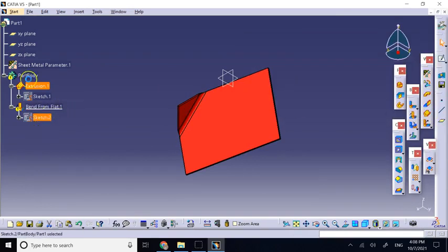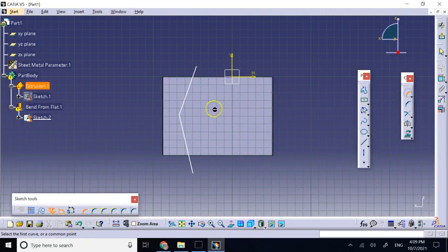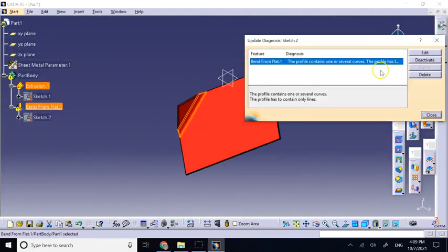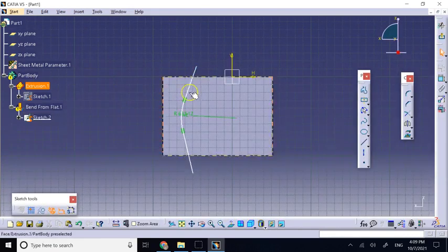So the most common thing, as I said, is a single line here, right? Now you might say, what if I put a fillet between these two lines and get rid of that broken corner? Can I do that? Something like this? And the answer is, again, no, because that arc, that fillet is not considered a line. So my suggestion is, really, if it's just in one location, you have to go with a single line, right?